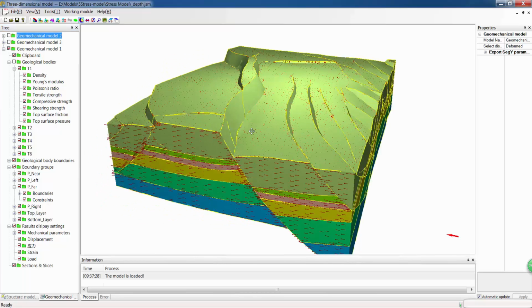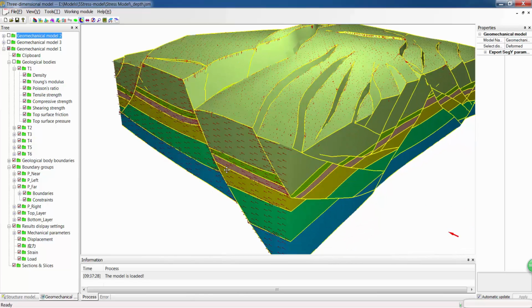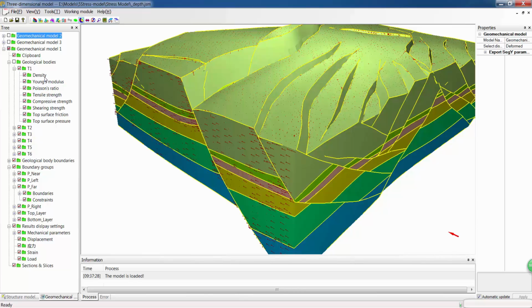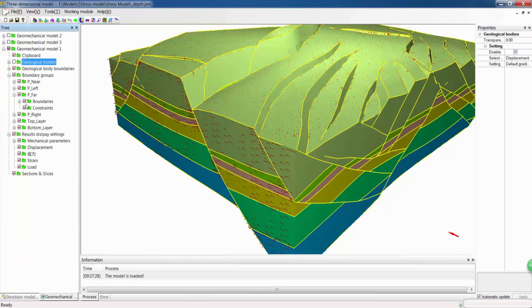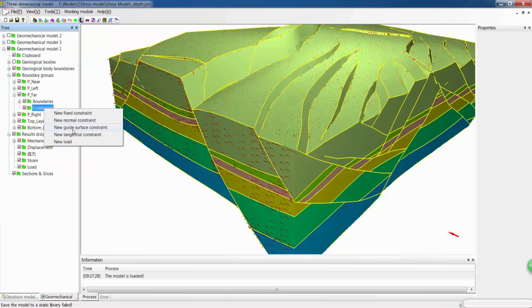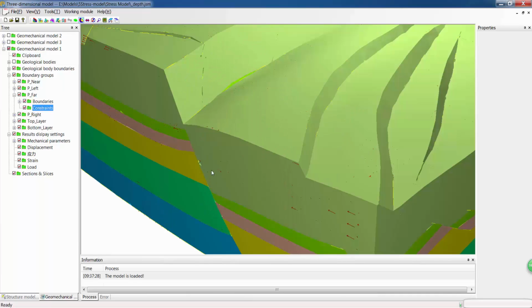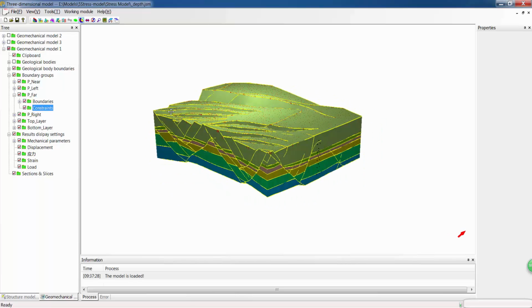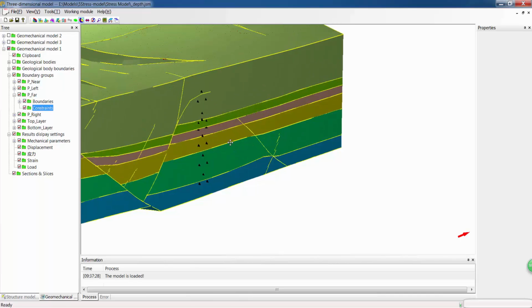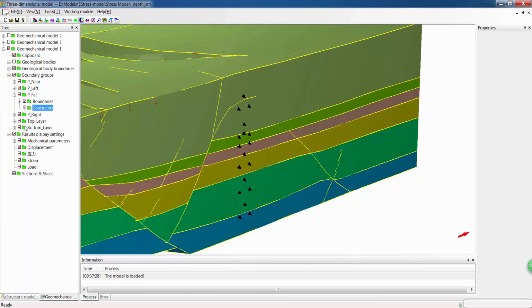It took 2 hours to build the structural model, 1 hour to build the geomechanics model. We need to specify some stress parameters, such as density, Young's modulus, Poisson's ratio, and others, and define or import certain parameters. Define base boundary conditions at each face of each layer, like external forces and/or constraints. On this face is shear stress. For this face is fixed constraints.